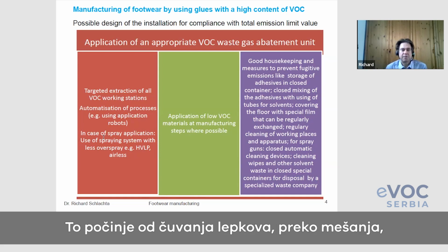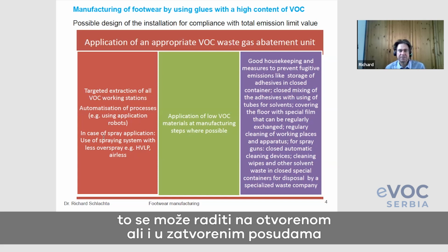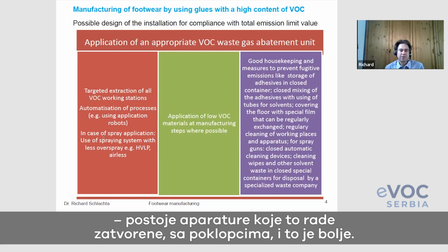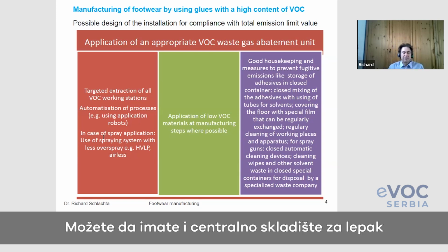It starts with the storage of the adhesives and the mixing of adhesives. You can do it open or you can do it in a closed way. There are mixing apparatus that work closed with a cover, so it is better you do it like that.